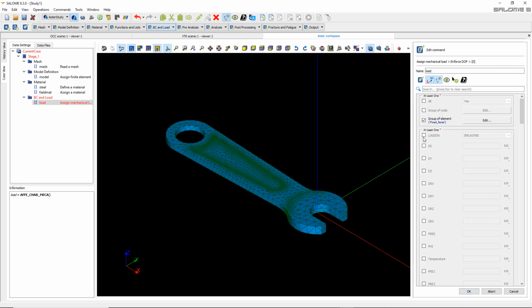And I'll use, so I could just go for activate that, all the 6 degrees of freedom, or actually just 3, because 3D elements only have 3 degrees of freedom, and I could just say, okay, this is 0, 0, 0, it's fixed.